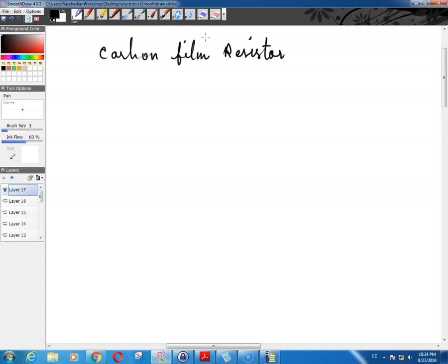Although when we get to that stage, I'll show you some places on the internet where you can find your resistors and other electronic components. And on the other hand, precision resistors contain a metal film deposited on an insulator. The thickness and width of the metal film determines the resistance. These resistors are called metal film resistors and are used in circuits for precision devices such as test instruments.